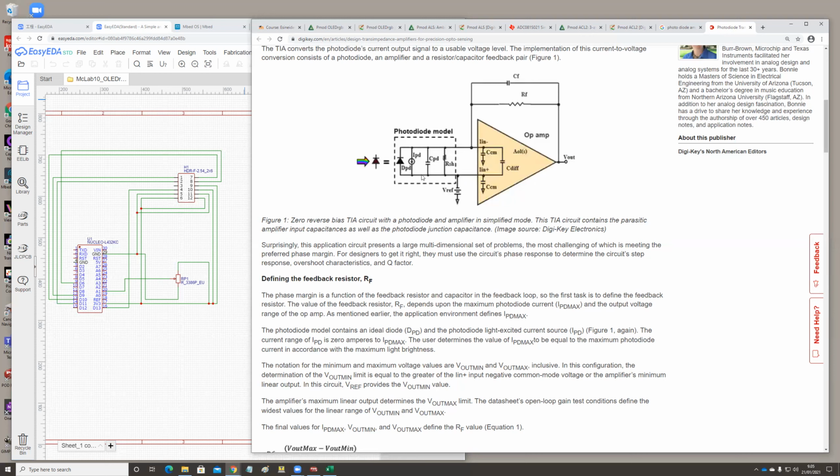And normally a diode is a device where the current is flowing in that direction, so through the diode. But in a photodiode, it's a little bit different. When the light is hitting the photodiode, it is creating the current in an opposite direction. So this photodiode is creating a current which is flowing in this direction. And that's some microamperes.